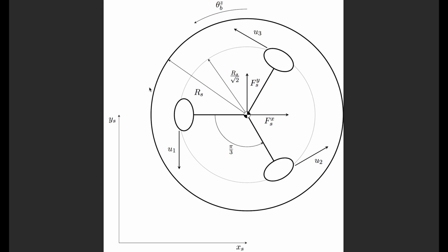In order to control the robot's 2-dimensional motion, we have to modify our model a little bit to account for this extra degree of freedom. This first picture you see here is the top view of the robot in the sphere. We modeled the robot with 3 wheels and 3 input torques shown here. Having these 3 input torques and 2 outputs, x and y, makes this model a MIMO system, unlike before.